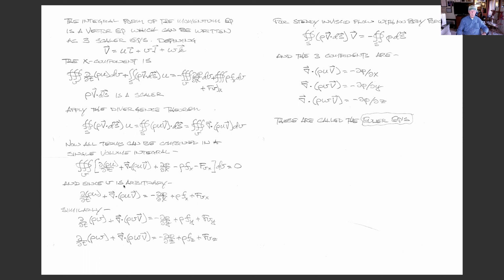And then we say, since the volume is arbitrary, you get 3 differential equations. And then we said, hey, we're going to have inviscid flow, and it reduced down to these 3 components. The one we will use most is the x direction Euler equation, but there we are. And at this point, we said it was steady and inviscid.